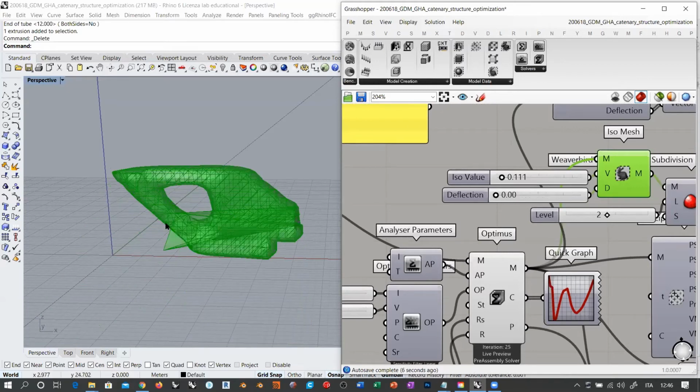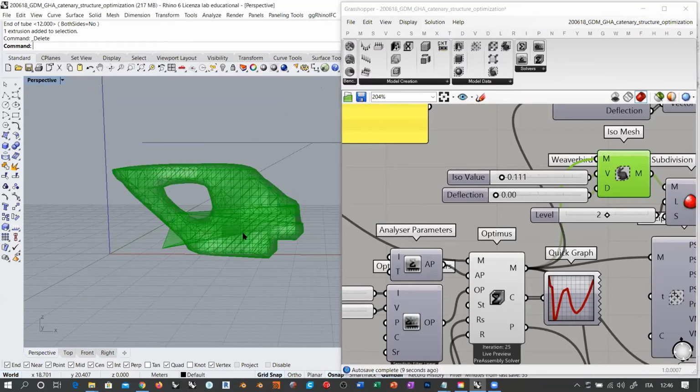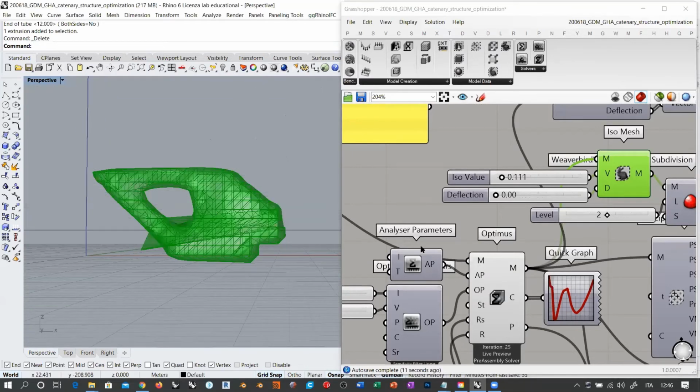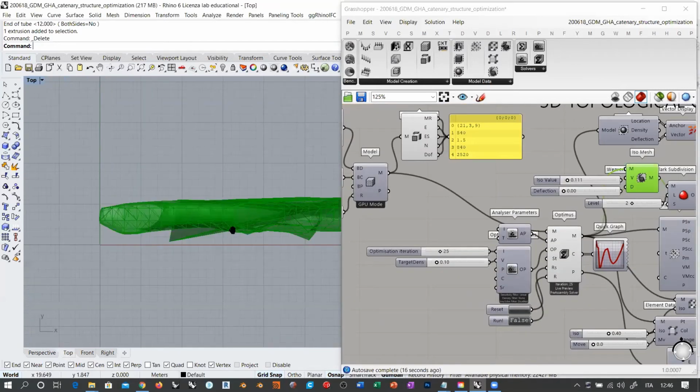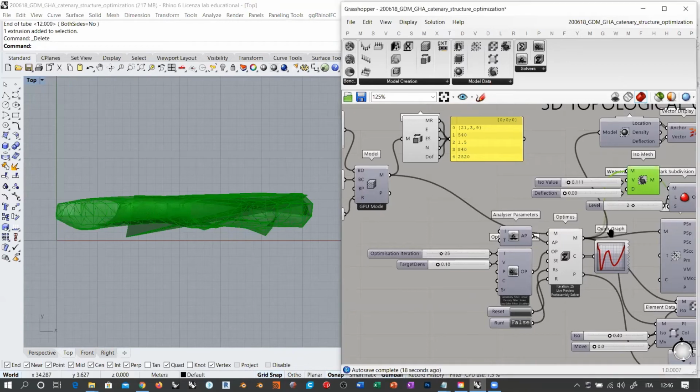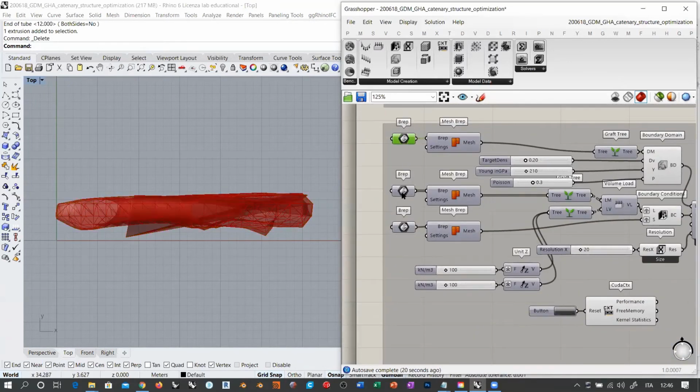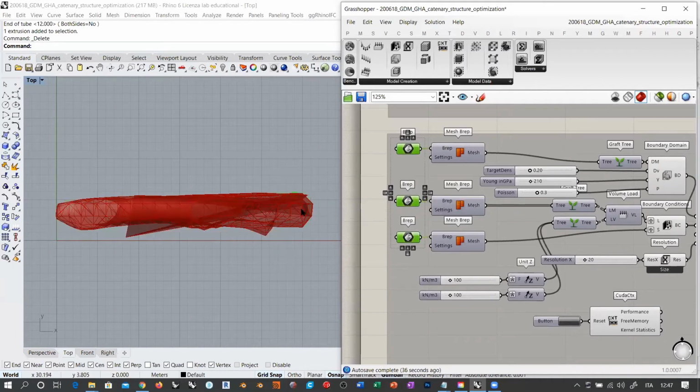You might notice that these weird triangles stayed in place, which is something that we can solve by increasing the resolution. Eventually, you might notice something like this, even if we have used a very symmetrical situation, as you can see. Everything is symmetrical with respect to the x-axis. So there is no particular reason for this object to come up shifted on the top of this system configuration, and having this kind of curvature. And this is because the resolution is quite low.